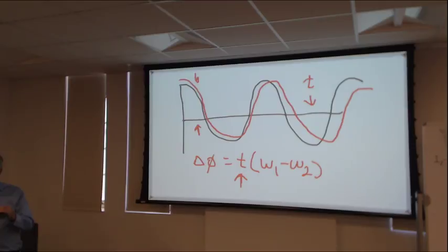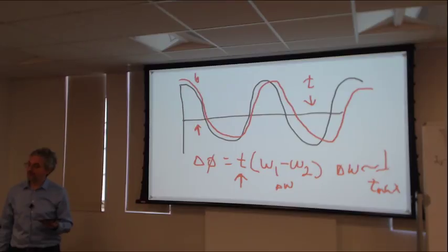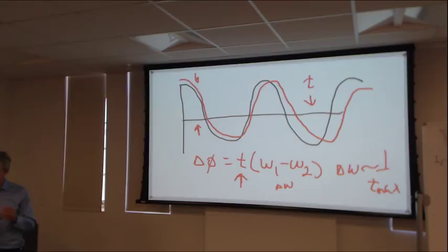So, this is something like the difference in frequencies. Roughly speaking, the difference in frequencies that I can resolve will be something like 1 over the maximum time that I observe. So if I have a very small increment to cover a big spectral width, I have to acquire many points in order to also have good resolution. And that's really a key trade-off with the Fourier method.